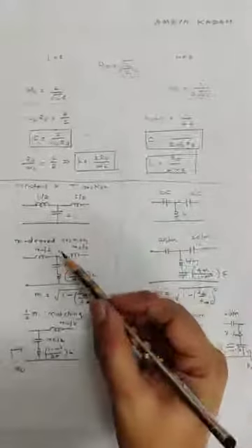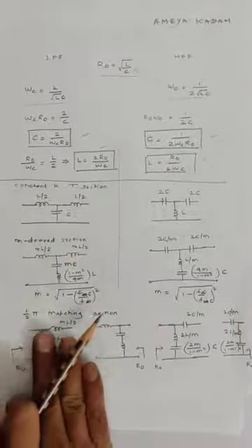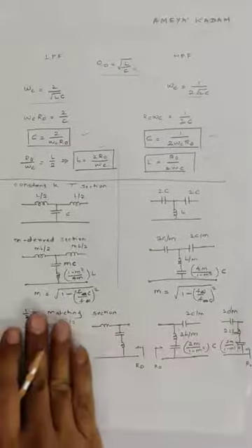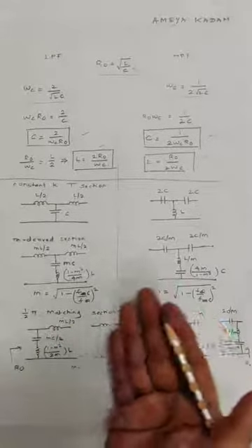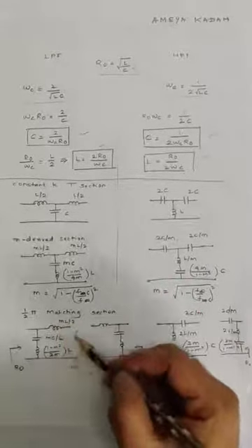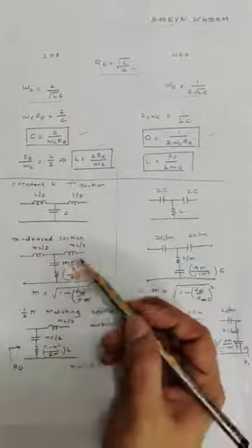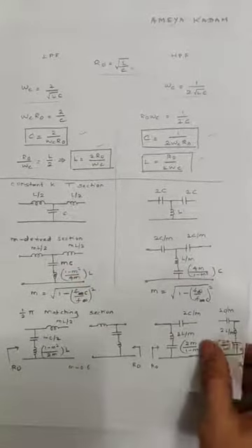The composite filter consists of 4 blocks: a bisected pi matching network, where m is equal to 0.6, will be used at the input side and its mirror image will be used at the output side. The intermediate 2 blocks are the constant k T section network and the m derived section. This we have seen in the last lecture in detail. Now we'll actually start solving the numerical.